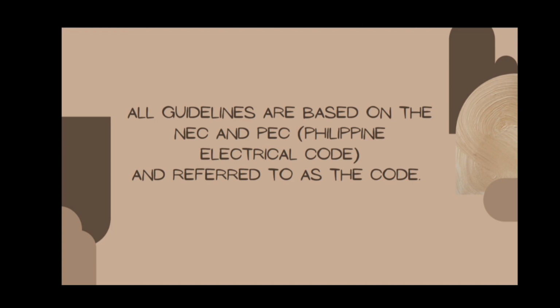14. Good practice suggests that the load should not exceed 1600 watts for a 20 ampere circuit and 1200 watts for 15 ampere circuit. Thus, A. Observe a maximum load of 1200 watts on a 15 ampere circuit with a maximum area of 40 square meters. B. Observe maximum load of 1600 watts on a 20 ampere circuit with a maximum area of 53 square meters.